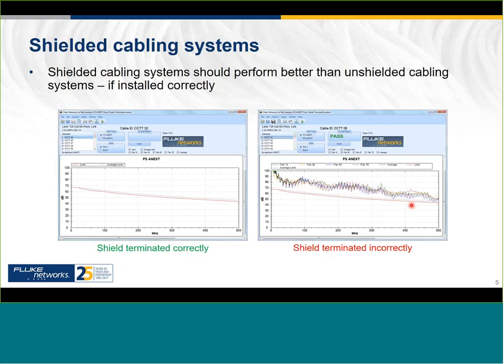So individual tests are now actually failing. However, we have to do an averaged measurement, and the overall average, which is the red line down the bottom, our results are not touching that line, so overall we're allowed to give this a pass. But as you can see, it's a very near thing.